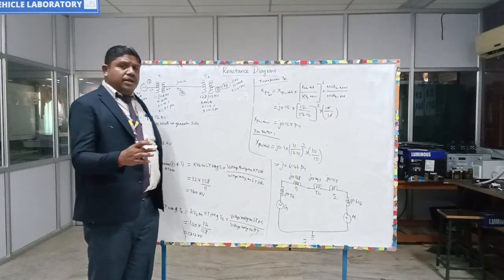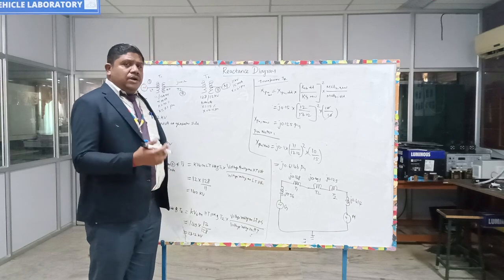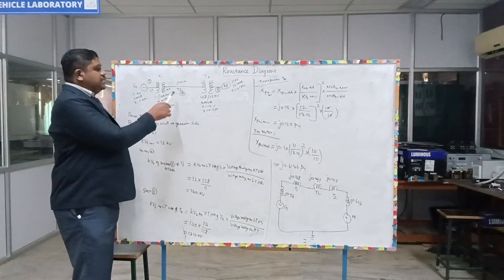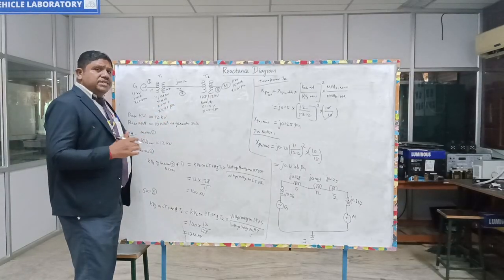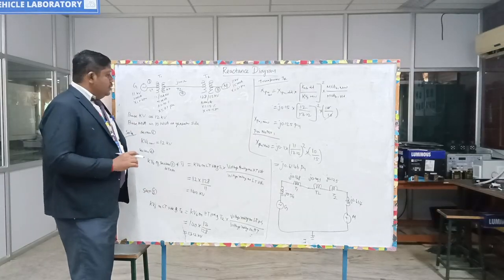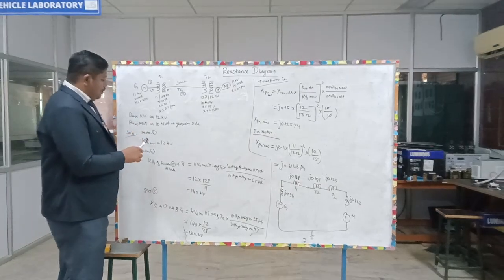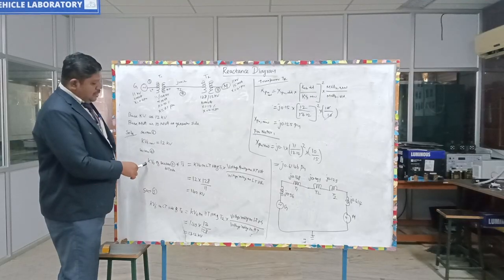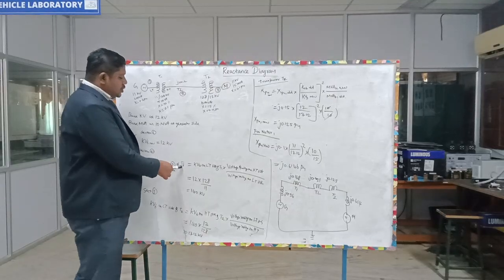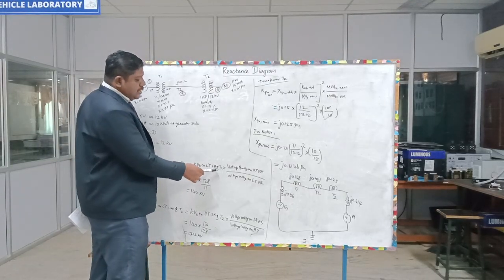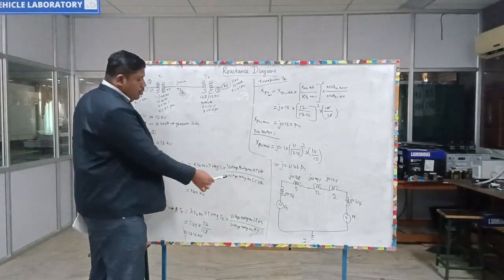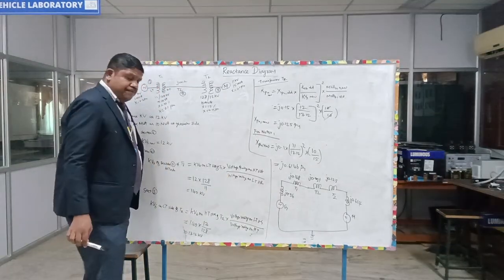So just a short recap. What do we have to do? We have to go with the reactance diagram, and from that we have to identify the sections wherever the voltage changes. We have to calculate the new kV base at that section. So for that we have the formula: kV base new on the LT side of transformer 1 is equal to kV base on the LT side of transformer 1 into voltage rating on HT side by voltage rating on LT side.